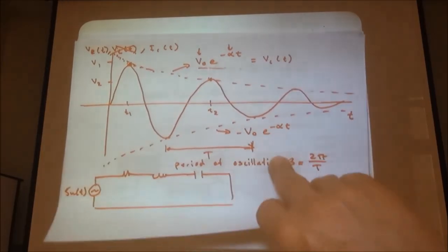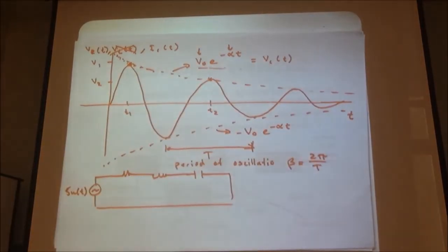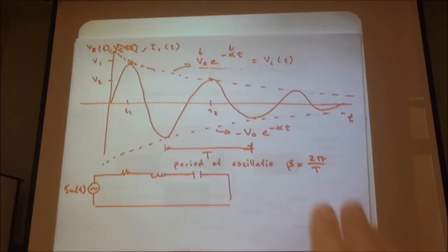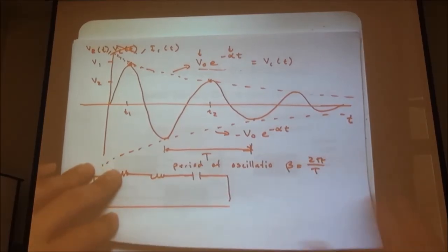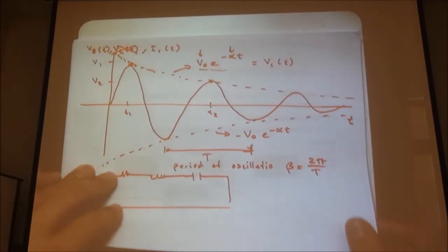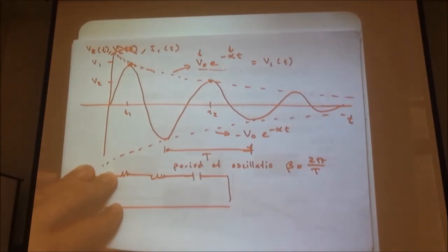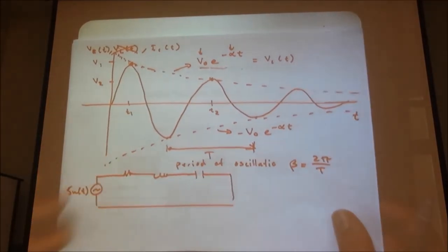So, there's a little bit of math. Just like in the strongly overdamped case, we looked at one dominant root. Well, and that gives us something we can use or compare to measurement. Here, you can directly measure the period using the discovery board. You can find these exponential values, and so you can compare this. So a little bit of math back and forth, but comparing measurement to circuit calculations, very, very reasonable.